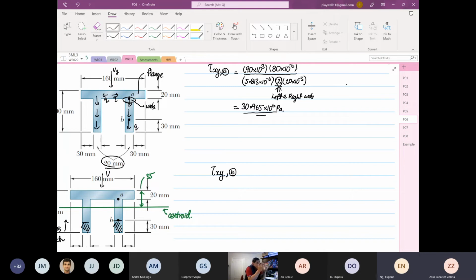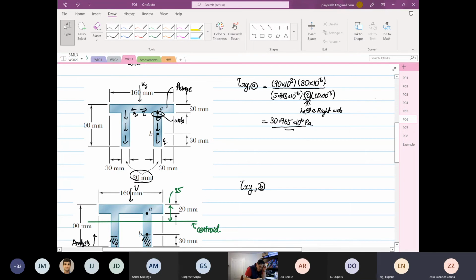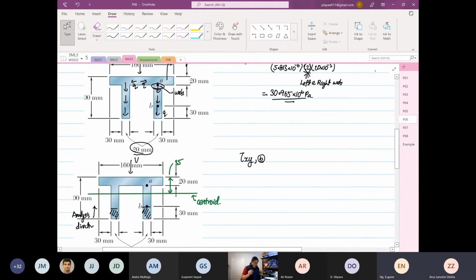Jazia, this is just the beginning. Let's learn the fundamentals first. It's not necessarily calculating the weakest thickness. If now I want you to calculate at a point down here called alpha, what thickness will you use? You use 160, yes or no? So don't get ahead. Later on, we go into that aspect. So now more important is the shear stress at XB.